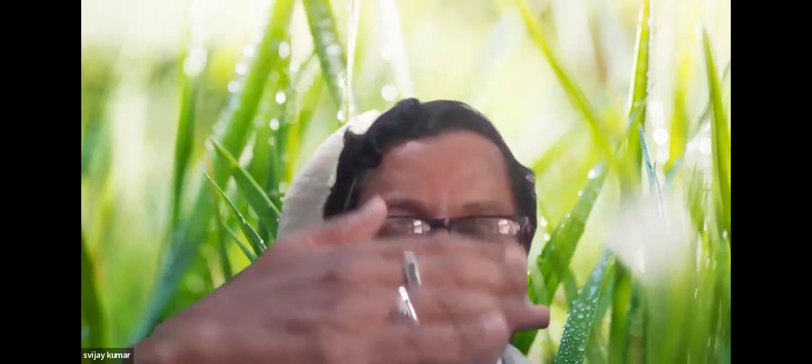But again, you will have to keep in mind that if the water spray is very heavy and the plant rooting system is very shallow, then you will have to be careful. You will have to select a nozzle which throws water more in the form of rain and not heavy particles of water. The main concept you will have to understand in a sprinkler is, when I throw water, I want the water to percolate, not disturb the roots, and it should not start running away from the field.